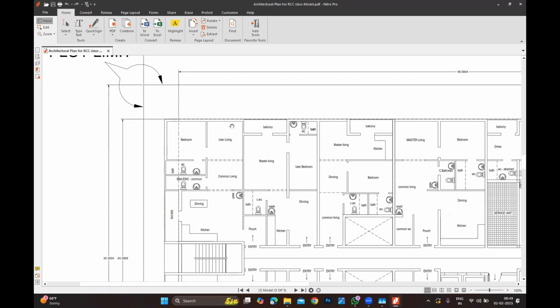If anybody says I have done value engineering by reducing the reinforcement of the columns or vertical elements, actually it is not value engineering. You are taking a spoon of water out of the flow. Say, for example, in a 100 million project, they are going to save like 1 million. A considerable saving is at least a minimum of 5%. If you're talking about 100 million, at least 5 million. If I'm saying 1 million, why should I waste a month to redesign the entire structure? Understand? Okay. So what is the next point we discussed?